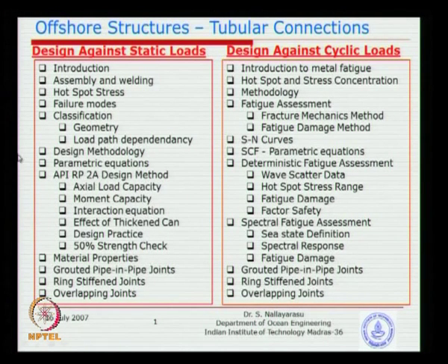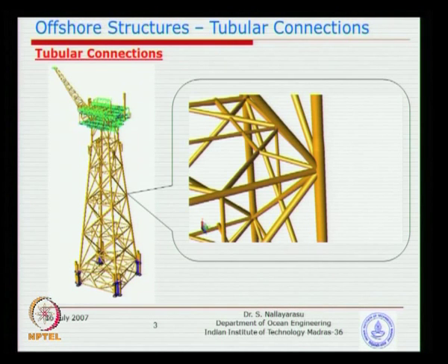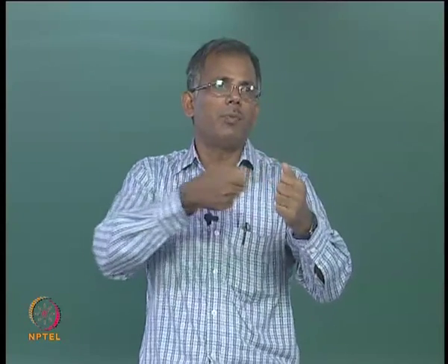And then we will also look at what particular material is susceptible to failure in the connections. If you go back to this picture, one important thing you will realize is that each of the members is going to get loads from any direction. You just can't predict it, depending on the waves and the gravity loads. Some of them can be pulling away, some of them can be going towards the joint. Now, when you are pulling away, what happens? Imagine if you have a steel material, try to pull off.